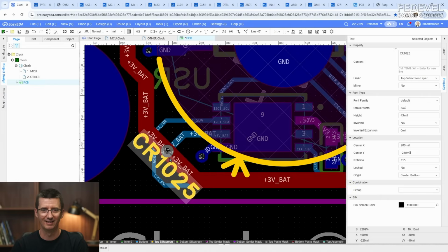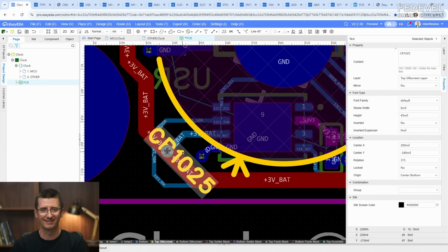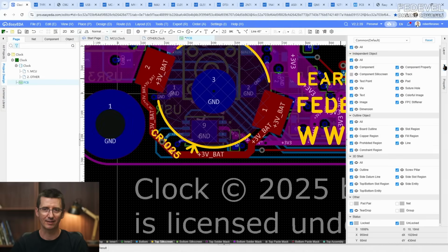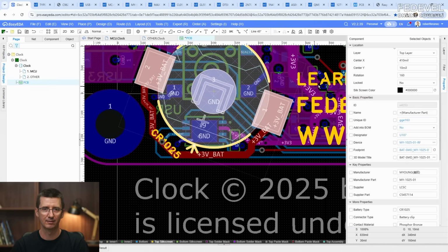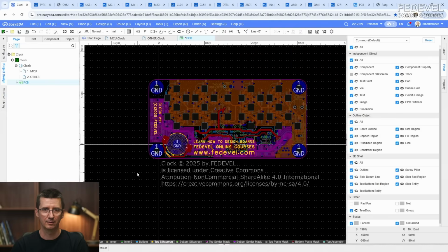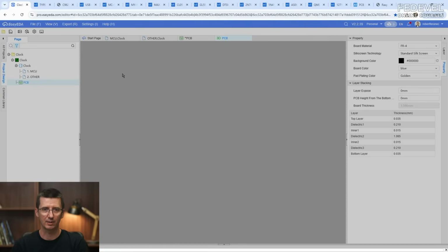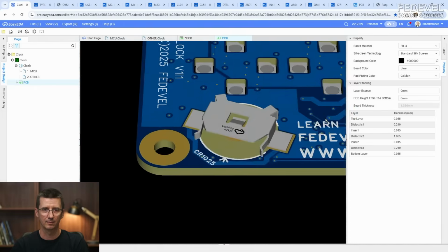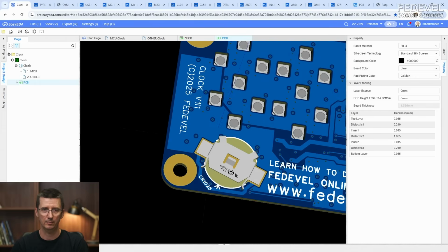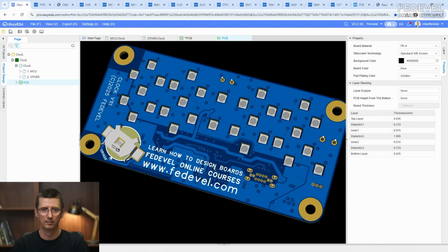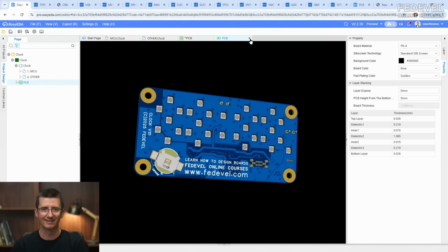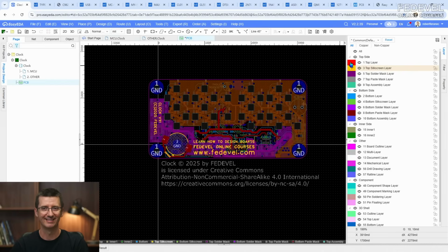There is just the VIA. VIAs can sometimes damage this text on a silkscreen, but I think it will be fine. Lock footprint and double check here. Okay, see, the blue color is removed, so this is perfect. I love it. I really hope you love your PCB.